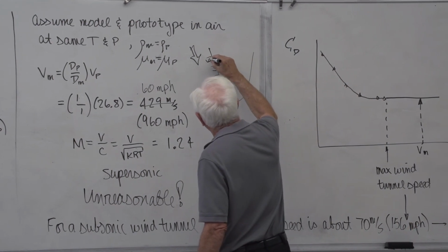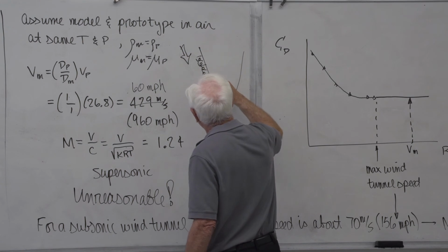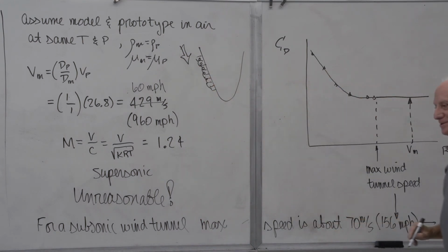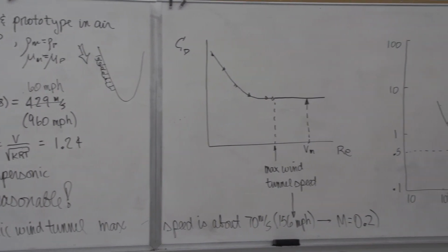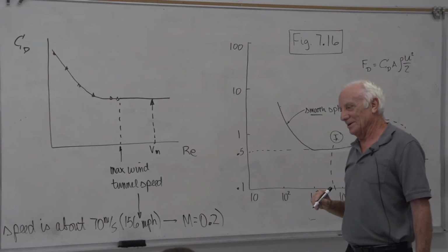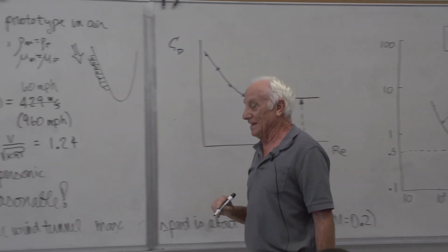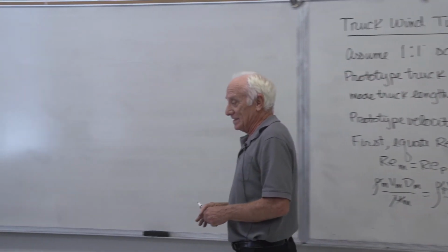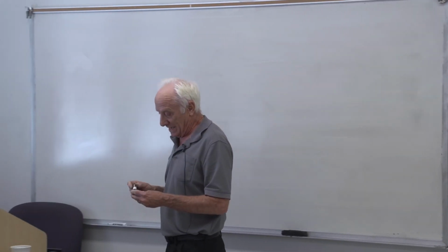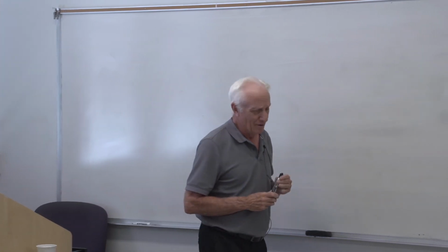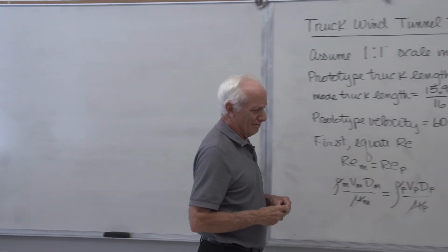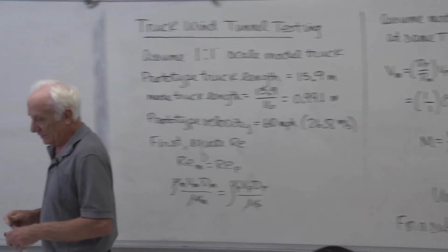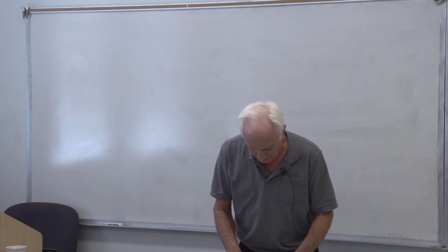And you're going to find out that there's swirling here because of roughness. This is where all kinds of sand and debris gets deposited, which means the ships have a tough time entering that area and docking. That's a big worry. You don't want your ship hitting a sandbar in there. So they do studies to see how bad the problem is and how to alleviate it. Okay, so model studies are done on everything, not just what we're talking about here.